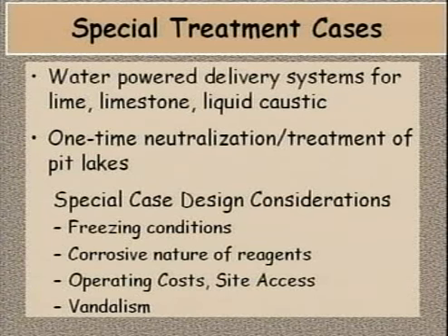The treatment of pit lakes with reagents is another situation that's a little different. Both caustic and organic materials have been used to successfully treat pit lakes. The big question is longevity, and it will be driven by the geochemistry of the pit walls above the water line. So to help preserve the effects of the in-pit treatment over the long term, some disruption of the ARD tetrahedron in the exposed pit walls will probably be needed. I've listed a few of the design considerations for these situations, but the list is far from complete.